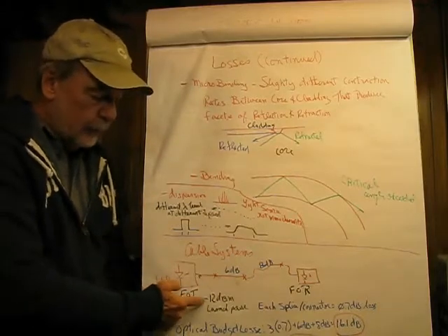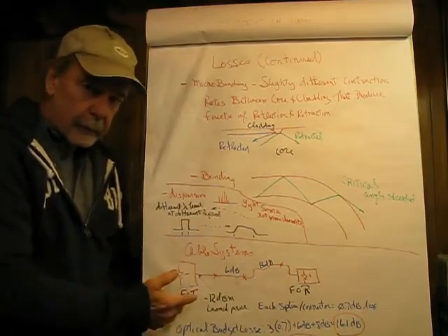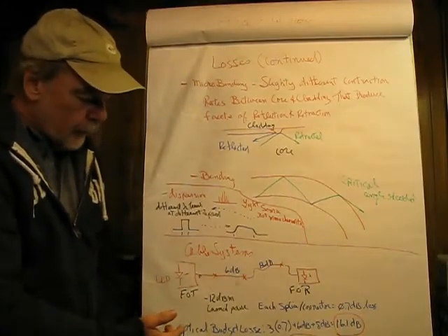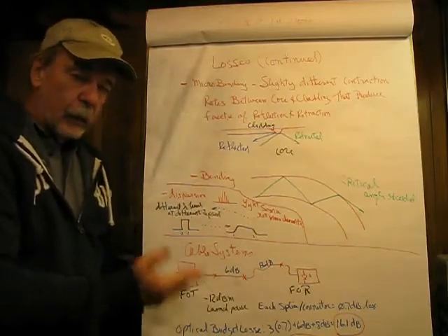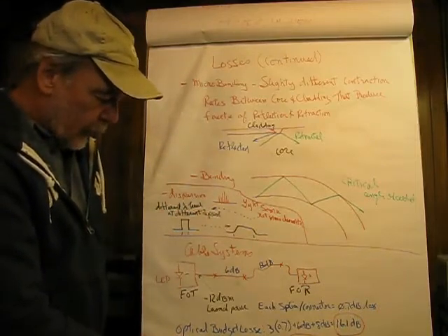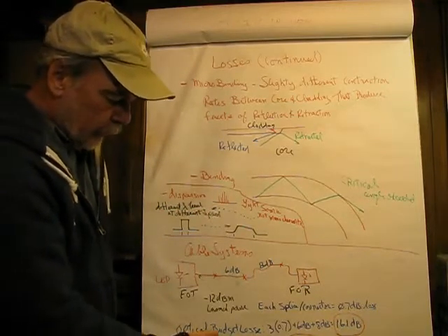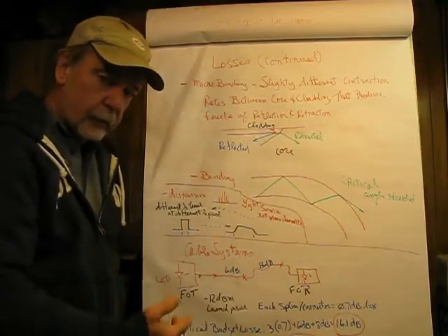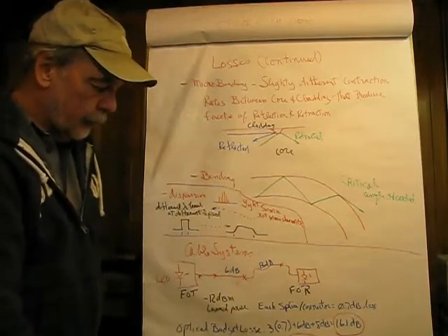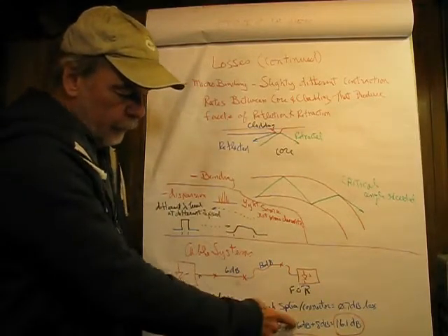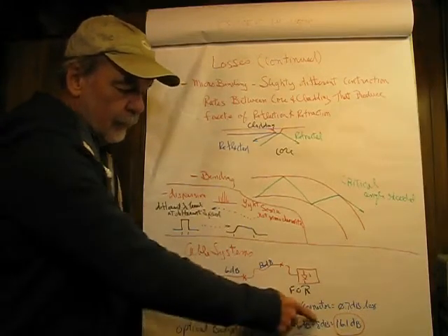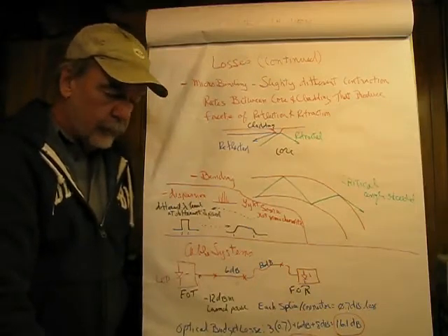Now remember, dBm is a power. It can be converted into watts. dB is a loss. It's unitless. It would be like, for example, power out divided by power in, where you have watt divided by watt. So what the equation would look like here, and this is called the fiber optic loss, or overall the loss budget, is 3 times the number of connector splices we have, plus the loss of one cable, plus the loss of the other cable, so the total loss of the system comes out to be 16.1 dB.